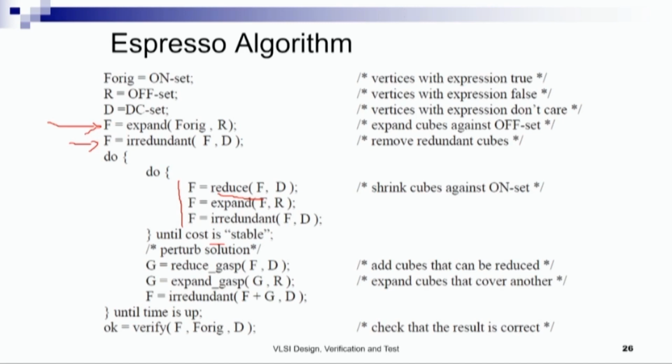The resulting new subcubes can then be expanded in a direction different from which they were expanded previously, and this possibly will give me a better solution. This lets different minterms be combined to produce possibly larger cubes. So when we expand in a different direction, we will possibly get different prime implicants covering a different set of minterms, and this prime implicant could be larger than the previous prime implicant that we got.